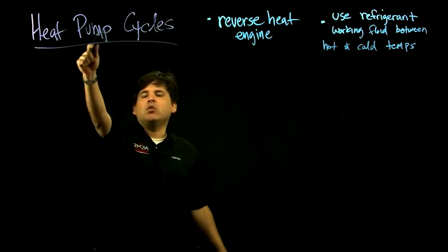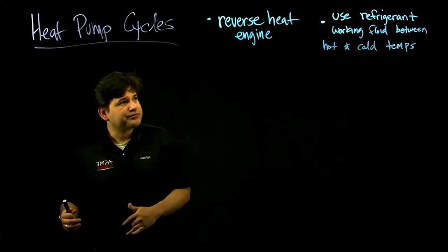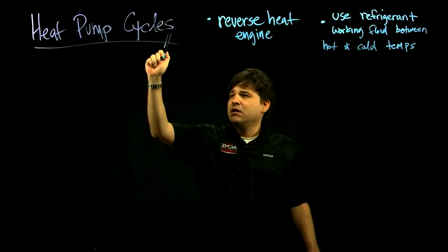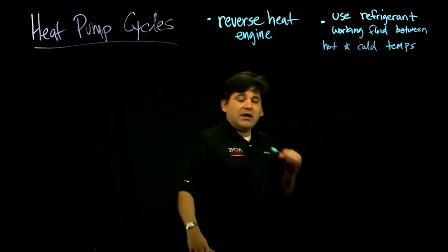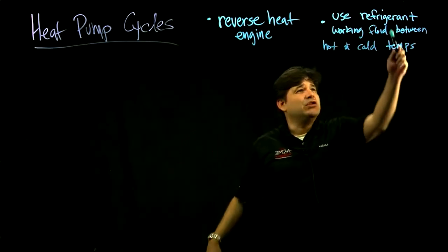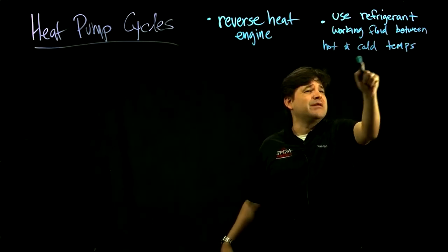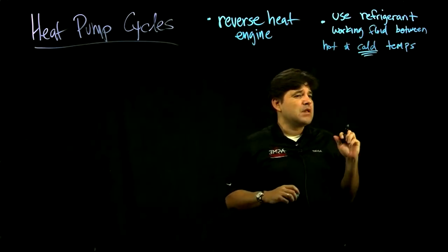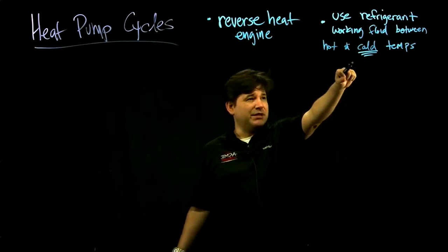for either low temperatures or high temperatures. So a heat pump, you want the high temperature. A refrigeration cycle, you want the cold temperature. But they're both heat engines operating in reverse. For the heat pump, you're optimizing and designing your system for high temperature. But even though you want this high temperature for your space applications, you still work around a refrigerant, which is designed to get to really cold temperatures specifically. So the refrigerant, even for the heat pump cycle, gets to sub-zero temperatures typically.